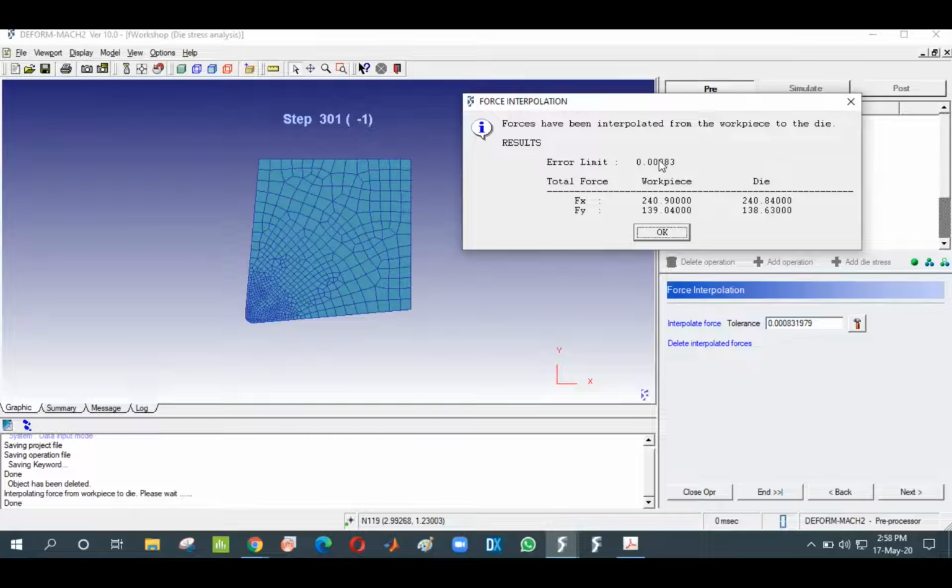in DEFORM 3D. I hope that you can be able to perform the machining simulation studies using this DEFORM 3D software on your own, because we have seen what are the issues that we can face. What happens when the database is not generated, how it will be intimated, when a correct steady state can be reached, that is the chip should be more and it should be away from the cutting tool, and all these things we have seen now. And now I will cut this and I will be moving towards the three-dimensional machining simulation.